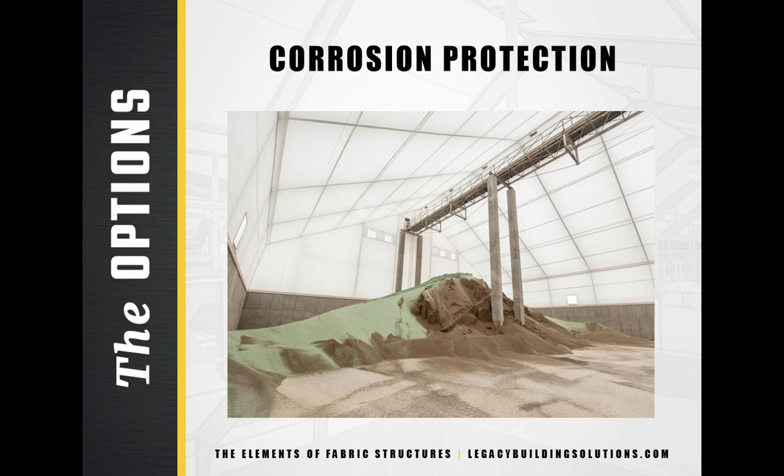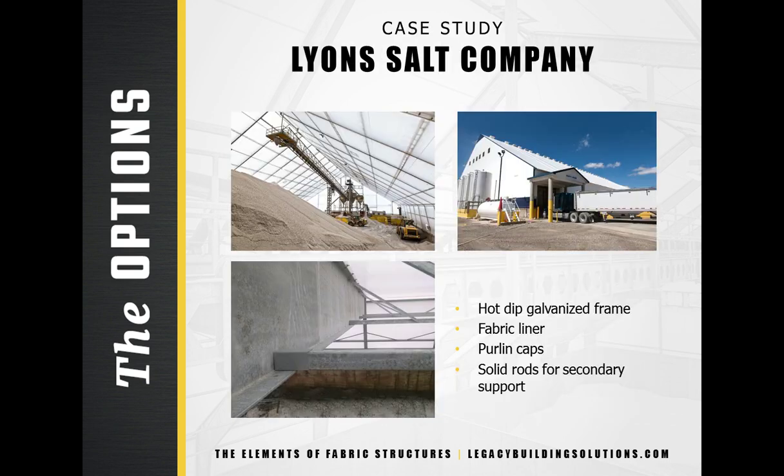Liners are permanently attached using a Keder system. All flaps are welded closed to create a solid barrier. Liners typically are made from fabric materials lighter in weight than the exterior building fabric. Access panels can be provided at regular intervals to allow the building owner to inspect the frame. Lined buildings should have a separate ventilation system for the cavity created by the liner to prevent moisture from building up on the steel components.